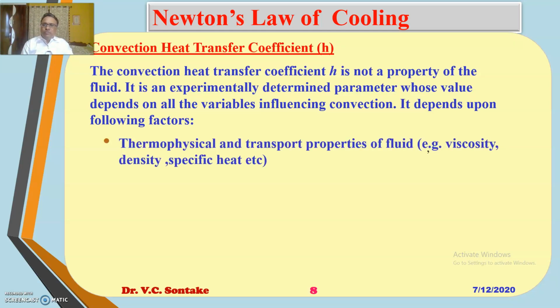The first factor upon which the value of H depends is the thermophysical and transport properties of the fluid, such as viscosity, density, specific heat, etc. Nature of fluid flow: whether the fluid flow is laminar or turbulent will also decide the value of H. We will be discussing laminar and turbulent flow in subsequent lectures.